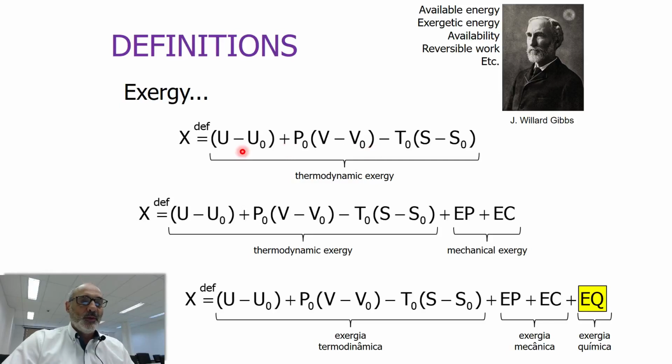So an important aspect of exergy is that it also considers the properties of the environment. If you're analyzing, for instance, a power plant to be built on the equator, it will behave very differently if it's built on the South Pole, and this can be taken into account in a very straightforward manner by using exergy.